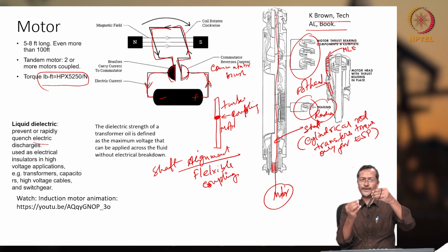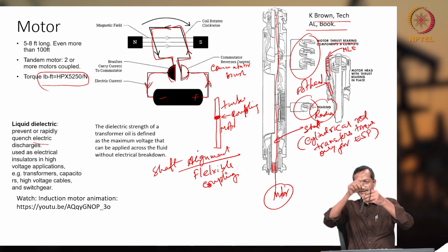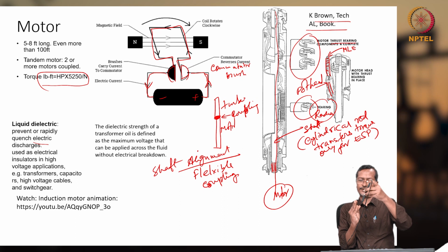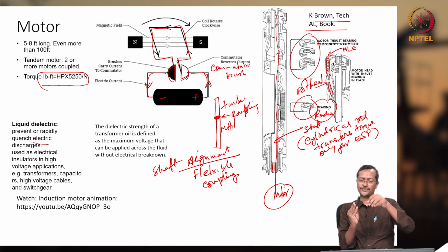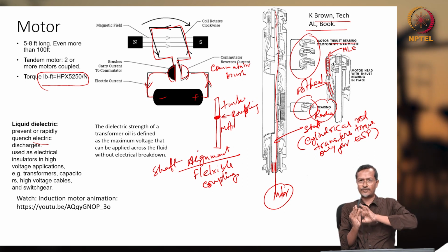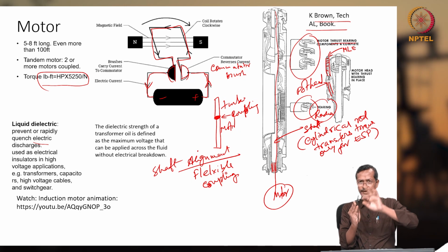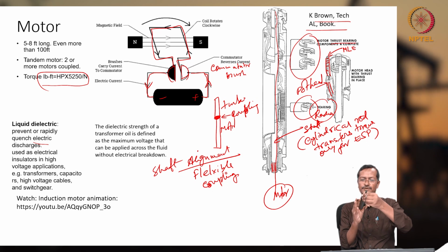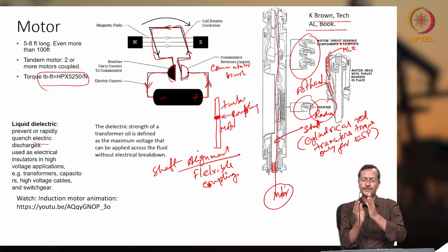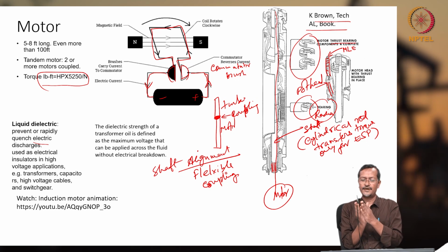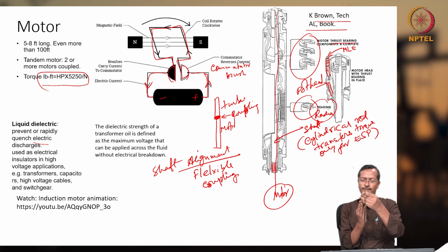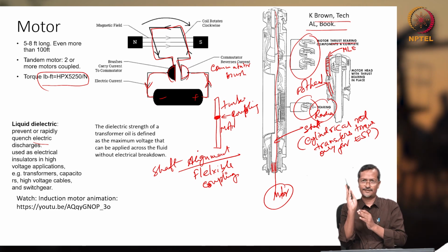So, the cable end will be coming, cable means from the surface electricity is carried, and I have the motor here. The motor will have some catcher like this. Okay. So, you just put it properly, so that it will be properly insulated. The motor will get electricity from the cable, but no water or other fluid will be entering there. So, it will be designed properly because you do not have much space inside the wellbore. So, you will have to design it in such a way that it will not create any insulation issue or any sparking issue, but it will be held properly. Okay.